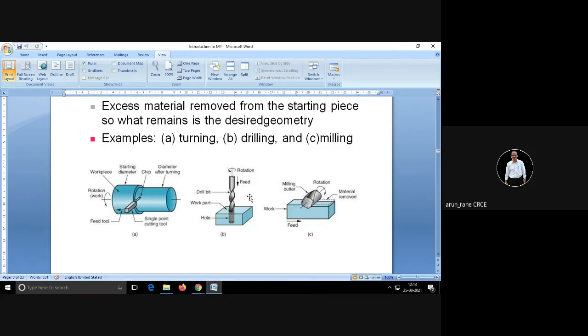So the spindle will get damaged, and once the spindle gets damaged, the machine cannot be used because you will lose the accuracy. If your spindle starts rotating eccentrically, meaning the bearings inside are damaged, your spindle will run out, and you will not get the desired accuracy.